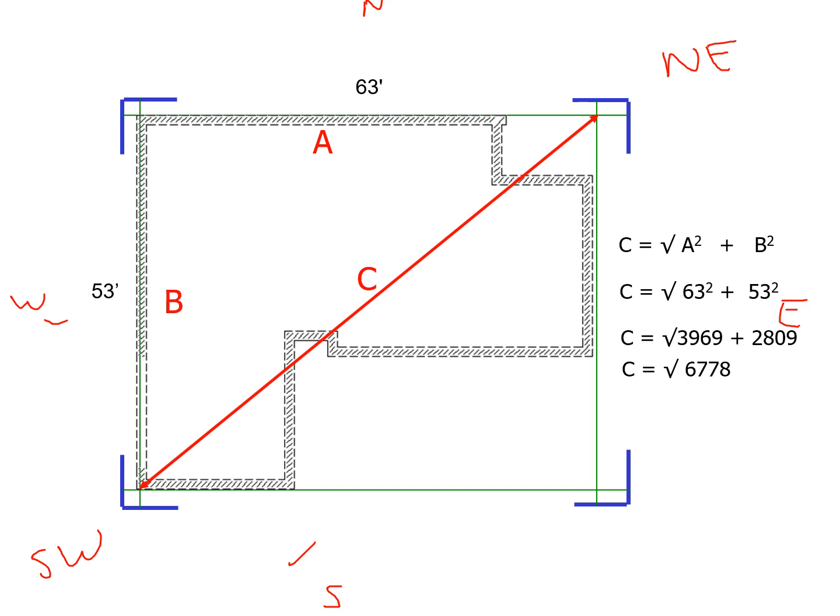When I hit my square root key on my calculator, it unsquares the number and tells me one side of the square. And it says that's 82.33 feet. That's 82 foot 4 inches. Remember, in the previous module when we went over our math, 0.33 is 4 inches. 4 inches divided by 12 is 0.33 feet.